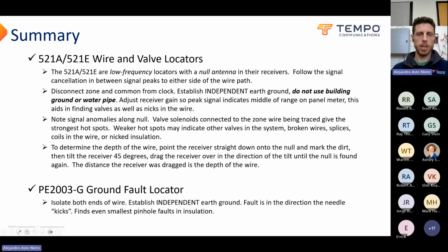The other thing you can do if there's a narrow section of sidewalk is tie some wire to a ground stake. The other end of that wire, tie it to one of your two spikes on your A-frame. You've now basically moved one of your spikes on your A-frame to wherever that ground stake is. So you can spike on either side of a sidewalk and picture just a bigger A-frame. And if it's telling you kicking to the left or right, it's giving you an indication of where that is.